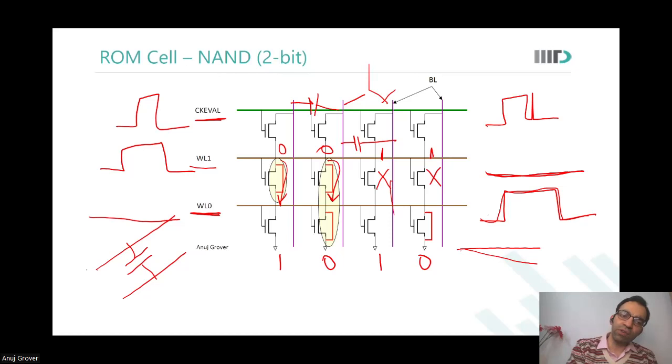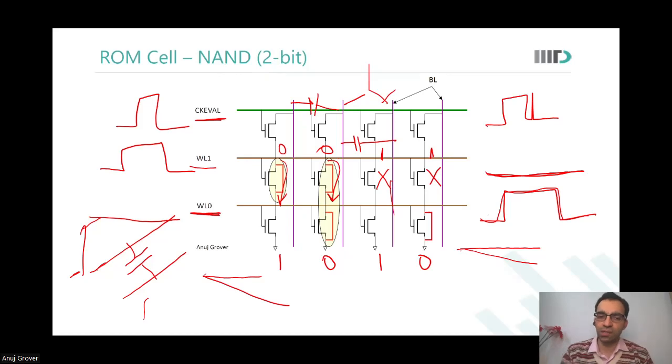You take one wire to VDD, and you see the other wire also starts to rise a bit. That is what coupling is. Over here, you are discharging one of the bit lines to 0. So the other bit line, which was not expected to discharge, is a floating capacitor, and it will also discharge a little. It was supposed to be like this.